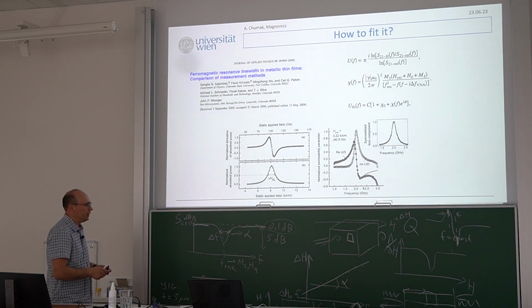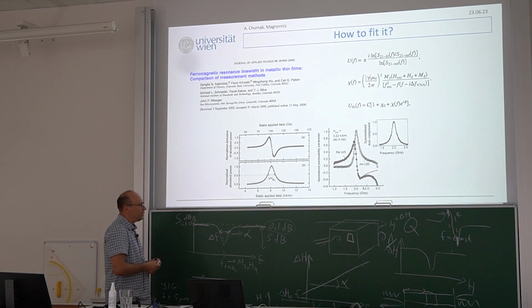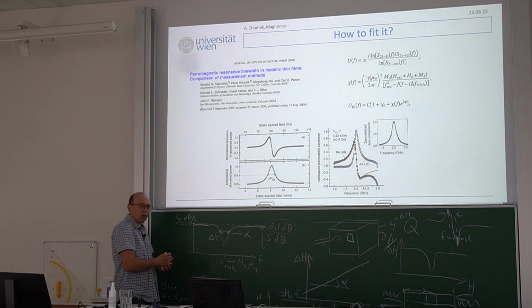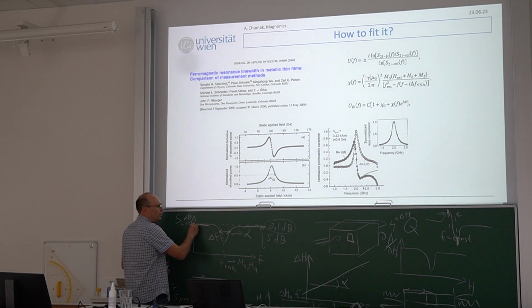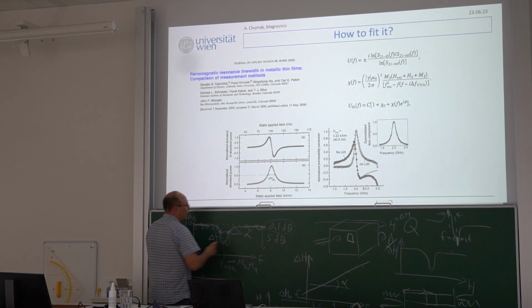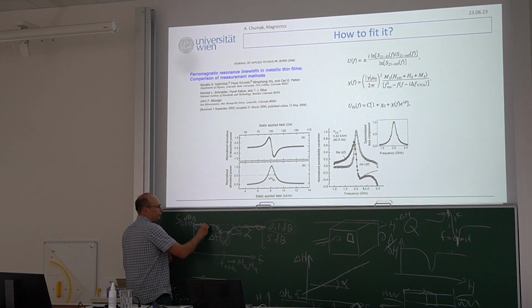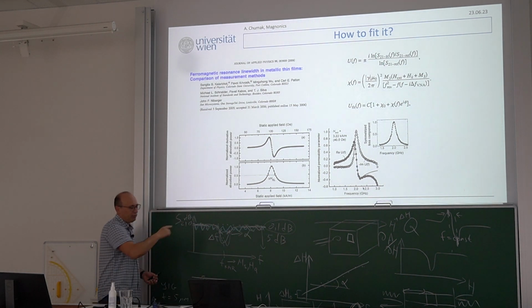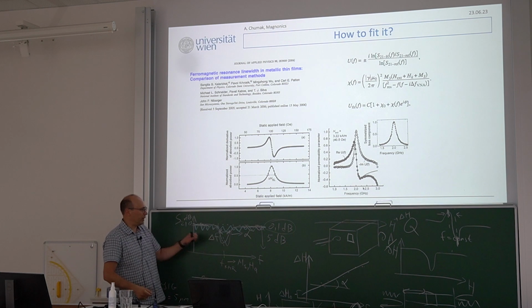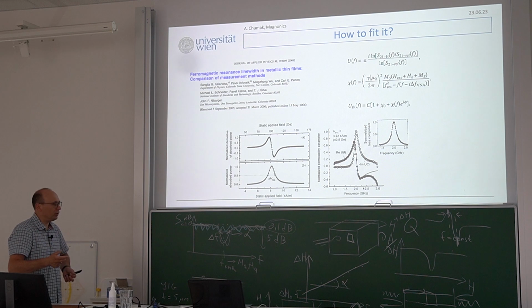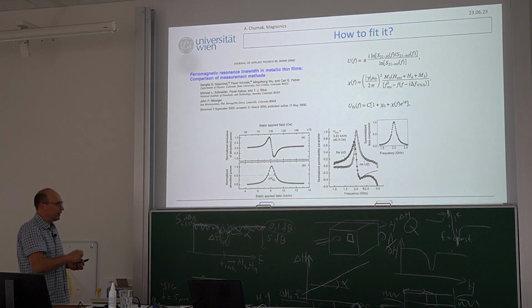How do we subtract the reference? You have your setup, you measure all the same but with zero applied field, and then you measure more or less this curve, with all these troubles here, so there will be some peak, something like this. Then you measure all this part; it should be the same. And then you subtract this blue curve from your useful signal, which contains FMR, and then you can go to a sensitivity of 0.01 dB or something like this. Very sensitive signal.